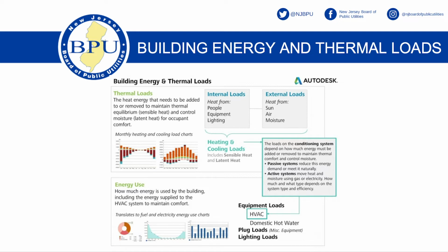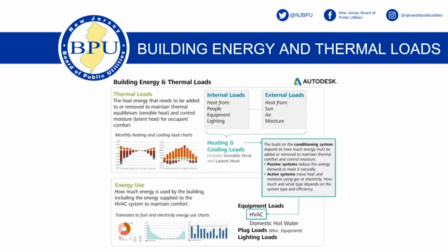How do we reduce loads? Well, we can put insulation on the building, right? We can caulk. It doesn't sound very exciting, but insulating the pipes and insulating the building itself and doing the caulking and getting all these holes that are inevitably there sealed up can save a lot of energy.